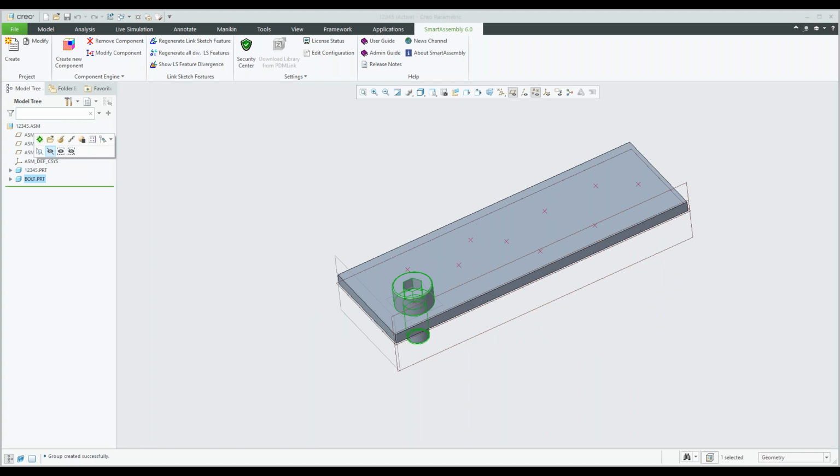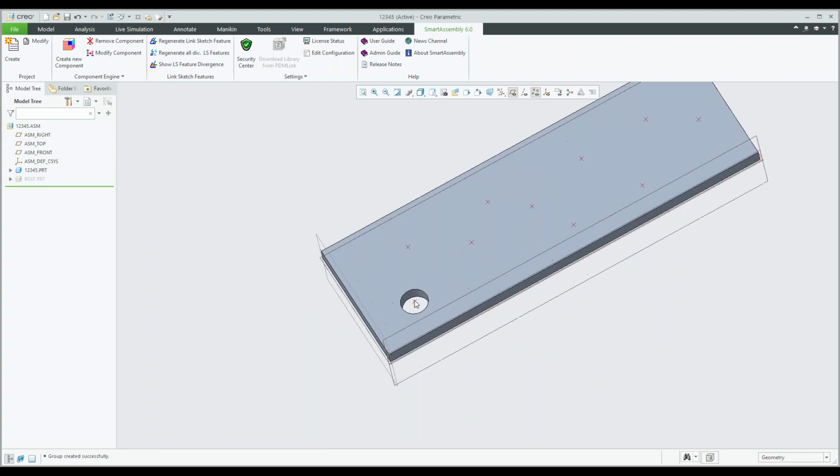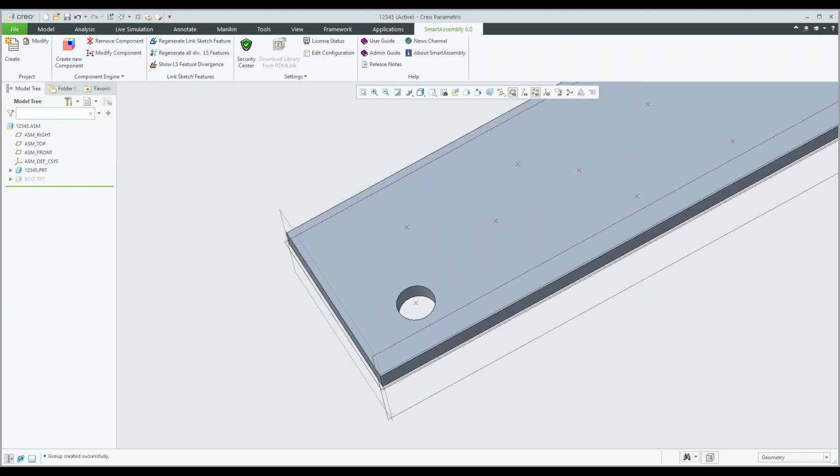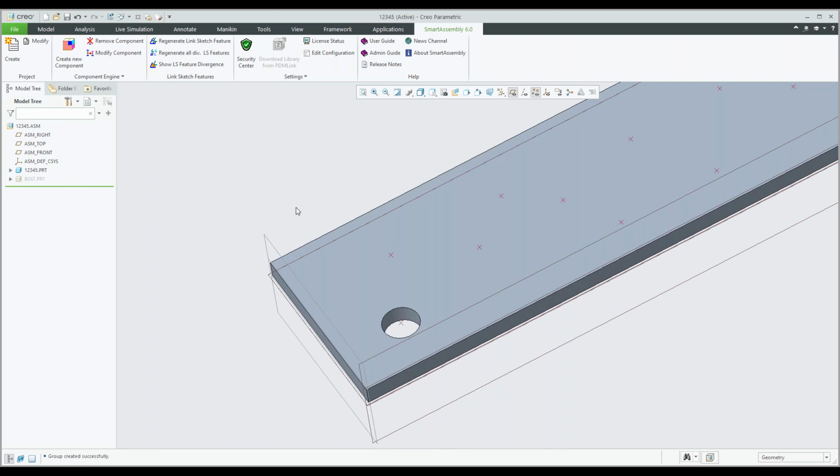So let's quickly hide the bolt. Let's see, so there's the hole as well. So we have a specific bolt with a specific clearance. We don't want to change that. As soon as the designer places that bolt, the hole size should be something that's pre-programmed, and the relief is in there. So that was part of that whole UDF that we've created in this scenario.